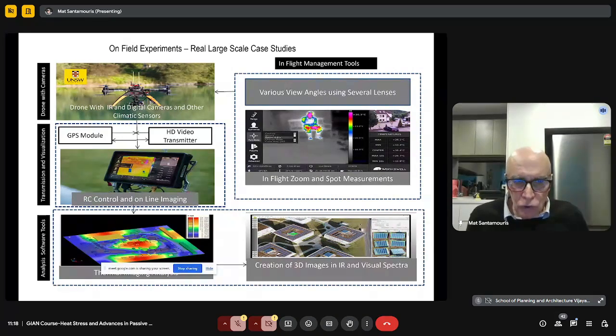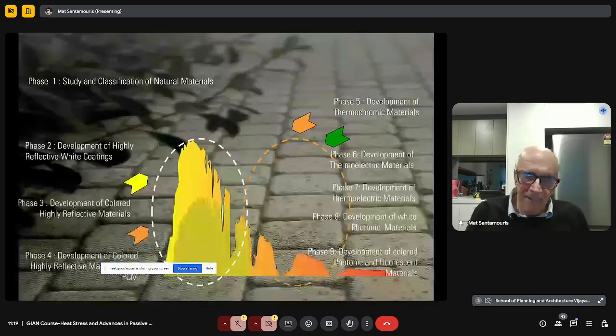Of course, this is not so simple. It is not just what the screen shows. We always have to correct for the proper emissivity of the materials. For example, if you have a camera flying on a drone and you measure the temperature of metals, what you have got is perhaps wrong because metals present a low emissivity. So in this case, you have to enter the software of the thermal camera and make a correction of the thermal emissivity in order to get the proper value of the temperature.